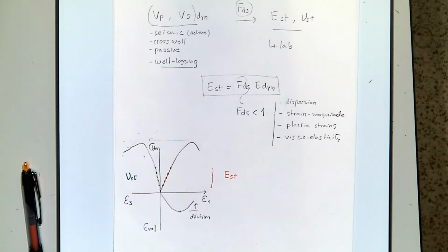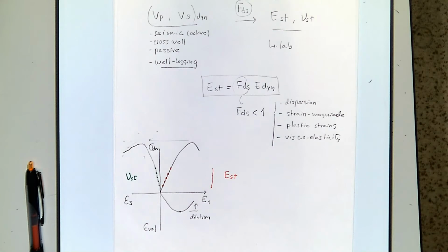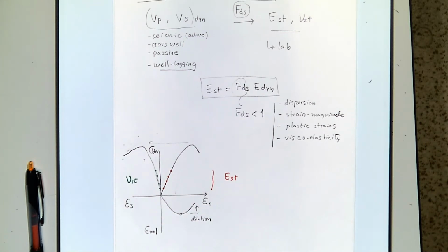So Robert, would you say that something like 50% of the ultimate strength is the yield strength essentially? Yes. Of the rock? Yes. So that in order to measure these elastic moduli, we should remain in the elastic range. And the elastic range is more or less in a domain of less than 50% of the peak stress. All right. So you know how to do this, right?